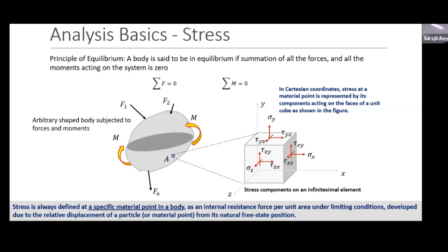Whether it is welding or machining, it is hard to work on. So you require more manufacturing time, more manufacturing cost, and even the raw material cost will be higher. So the cost and manufacturing processes will not be supportive of using stronger materials.